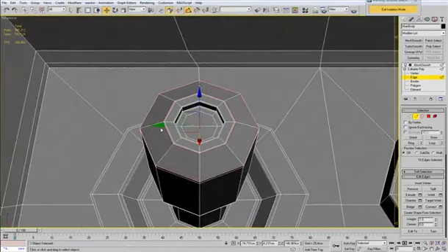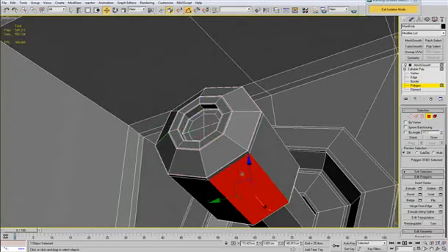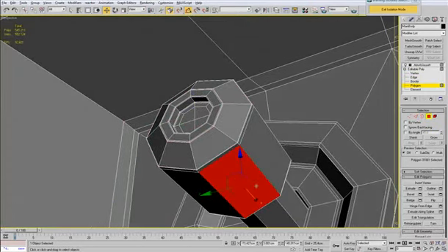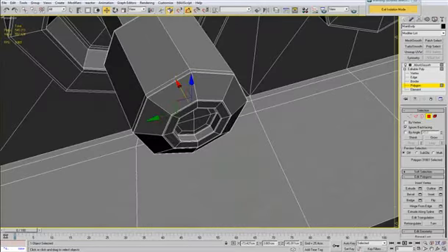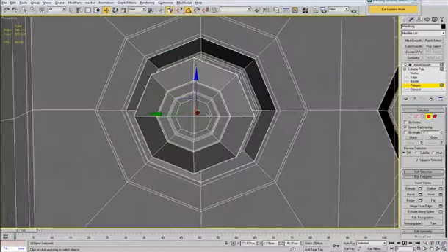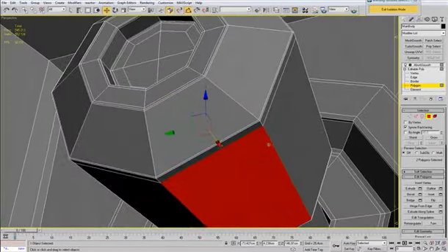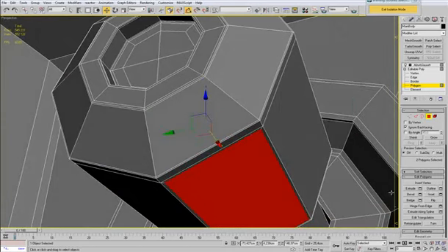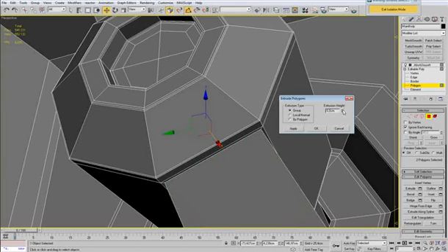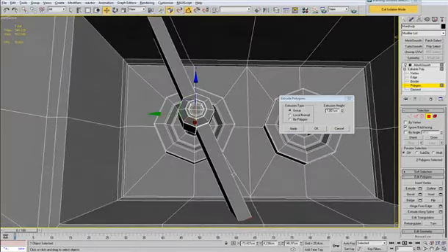Okay, so added a few connections there to harden the sides, and now I'm going to create the handles themselves, just selecting two of the opposite polygons here, and I'm going to perform a small inset and make an extrusion, a small extrusion at first, and then the bigger one.